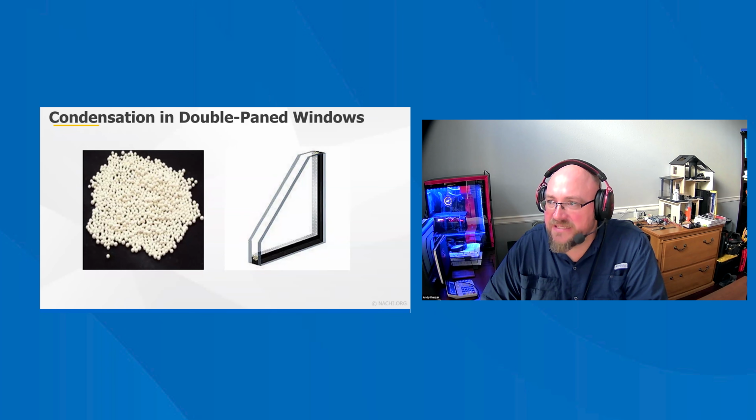If not for this substance, incoming air could condense on the glass. Silica gel has an immense surface area, which allows it to absorb water vapor for years. Eventually, the silica pellets will become saturated and will no longer be able to prevent condensation from forming. A double pane window that appears foggy has failed and needs to be repaired or replaced.